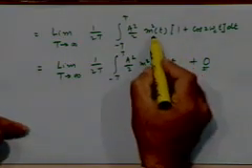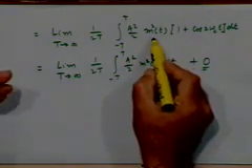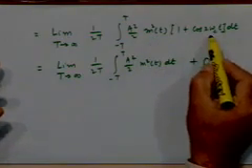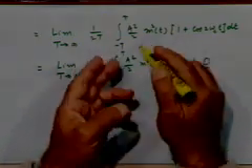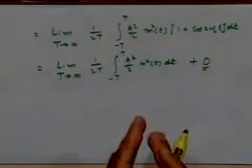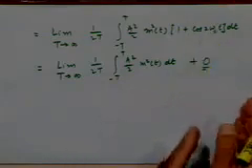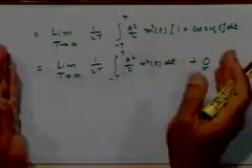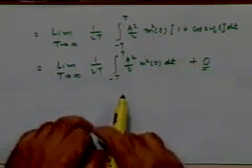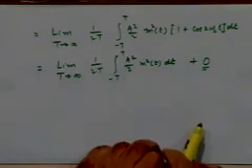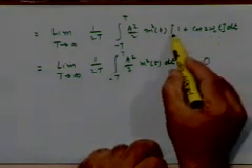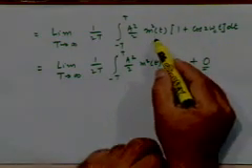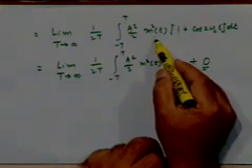Because m square t is a slowly varying waveform, right? Cosine 2 omega ct can be considered, we can consider this integral as integration cycle by cycle of the carrier, half cycle by half cycle. So over one cycle you can assume m square t is nearly constant, and the positive half cycle will cancel with the negative half cycle. So half cycle by half cycle, the value of the second integral would be 0, because cosine 2 omega ct is being multiplied by a very slowly varying function compared to its own rate of fluctuation.